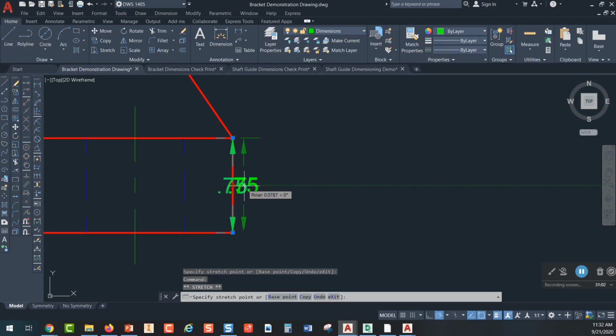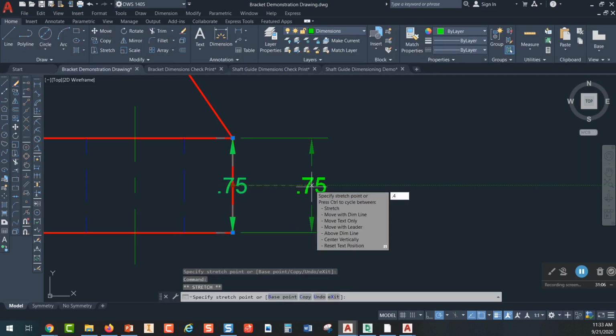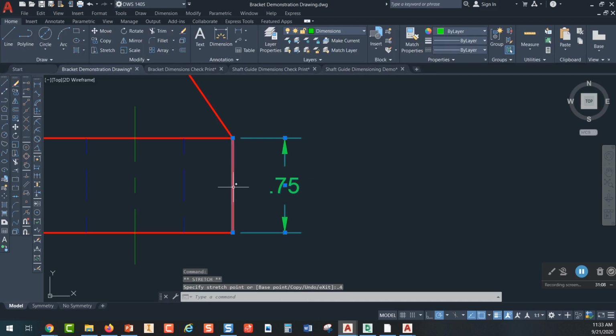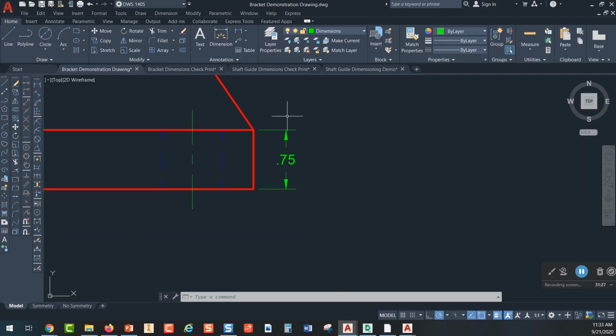Then pick it and hold down and drag it out in this direction right there and type 0.4 and press enter. So if I bring it all the way back to here and then I drag it, type 0.4, I can actually snap it over there to being 0.4. So that's two ways you can do it. You can use the offset of 0.4, or you can place the dimension, drag it onto the visible line, and then drag it to the right and type 0.4 and press enter.